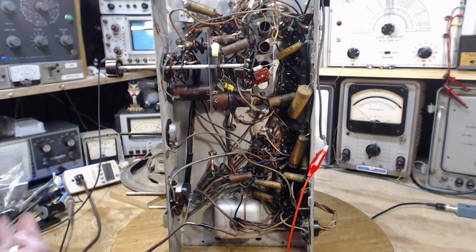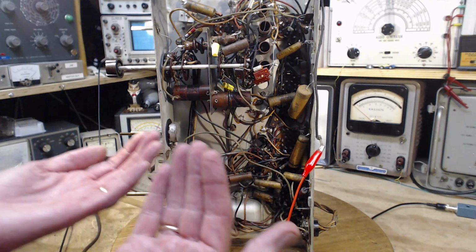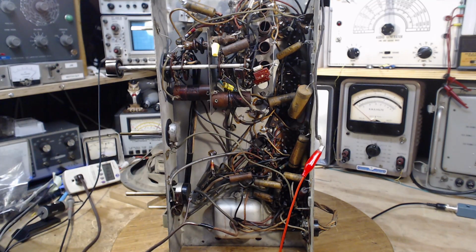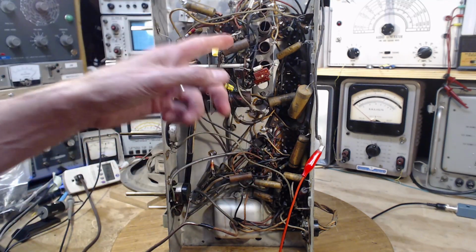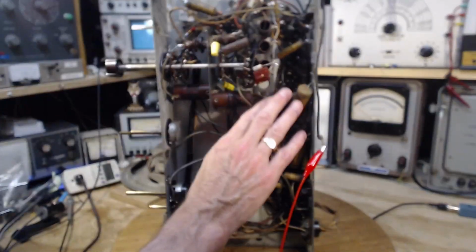Probably because of the lack of performance in the front end of the radio. Maybe a good place to start is the front end of the radio and start changing out capacitors there before going too much further. Typically I start with the audio and kind of work my way back through the radio to the front, knowing that the sound is working good. Well, there's lots of sound coming out of it right now, so we can assume the audio circuits are okay, and just focus on these radio circuits. So it would be capacitors that are tied in with these coils and stuff, all the stuff up in this area here. We change all these out and then do another performance check. And I may want to take a moment, and all these ones are later on in the radio.